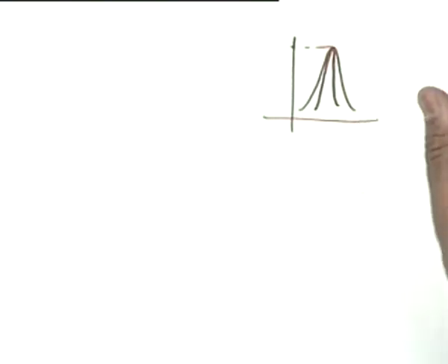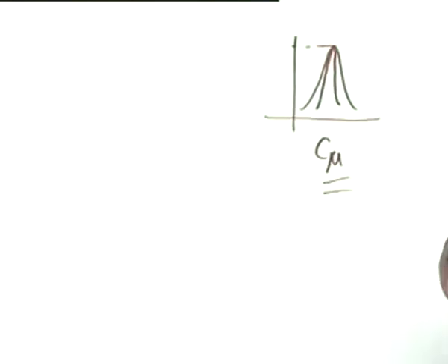But we showed last time that even using two tuned circuits in a single amplifier, single transistor, poses problems due to C mu. This is the menacing problem in the design of any high frequency circuit.